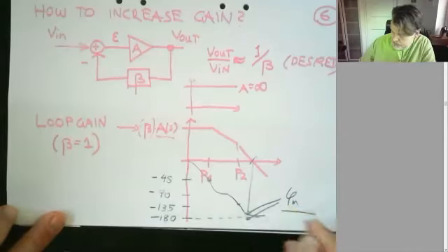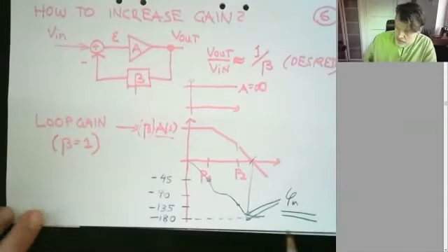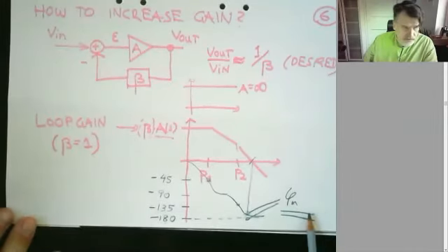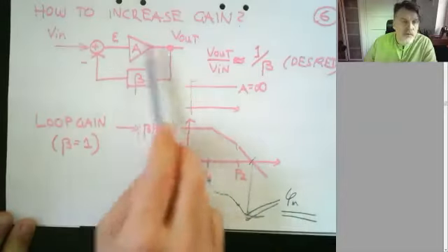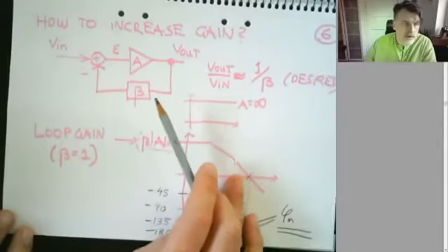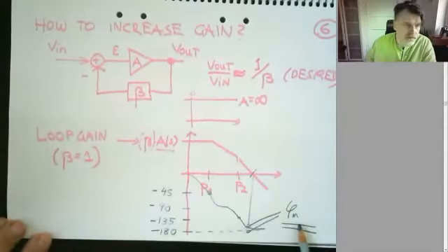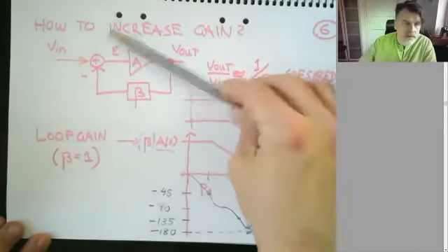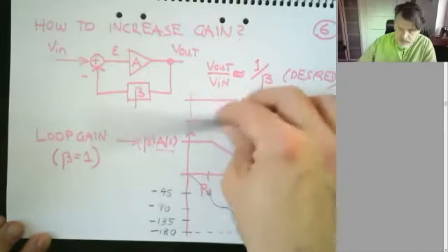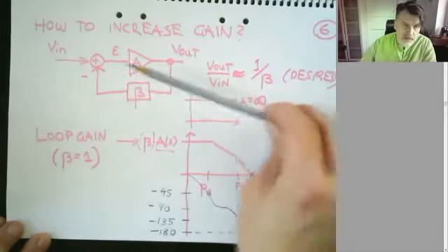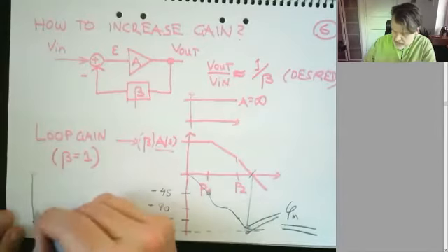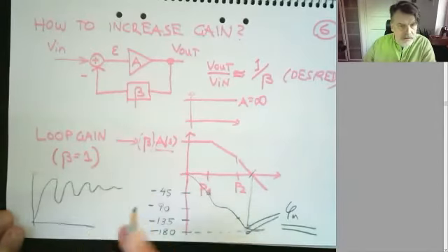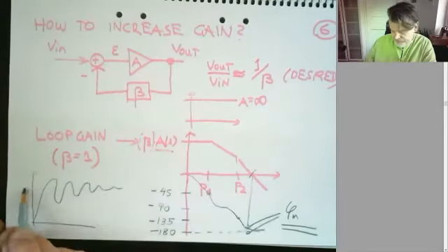Okay, so we need to guarantee a certain phase margin. This is still stable. If the phase margin is larger than 0, it's still going to eventually settle and give you a good number out. But the less the phase margin is, the more swinging you will have on the output voltage. There will be some settling behavior, which will depend on the phase margin.